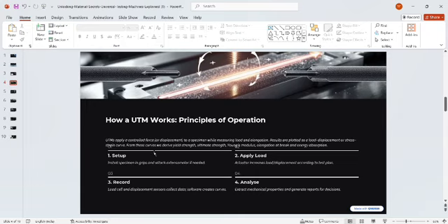From these curves we derive the yield stress, ultimate tensile strength, Young's modulus, elongation at break, and energy absorption. We measure how much load we are applying on the specimen and how much it elongates, and from this curve we derive the yield stress, ultimate strength, Young's modulus, elongation, and so on.